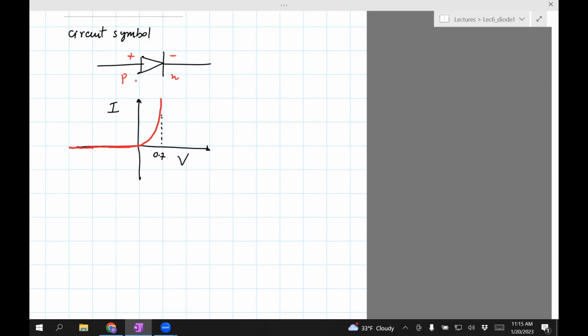And then at some point, it actually will go down here. So this is about 50 volts. And this is negative 50. And this is known as the breakdown voltage. So what happens there is that if you go beyond minus 50 volts, you'll basically fry the diode. It will no longer work. You'll damage the diode. So you wouldn't want to go to a great negative voltage.